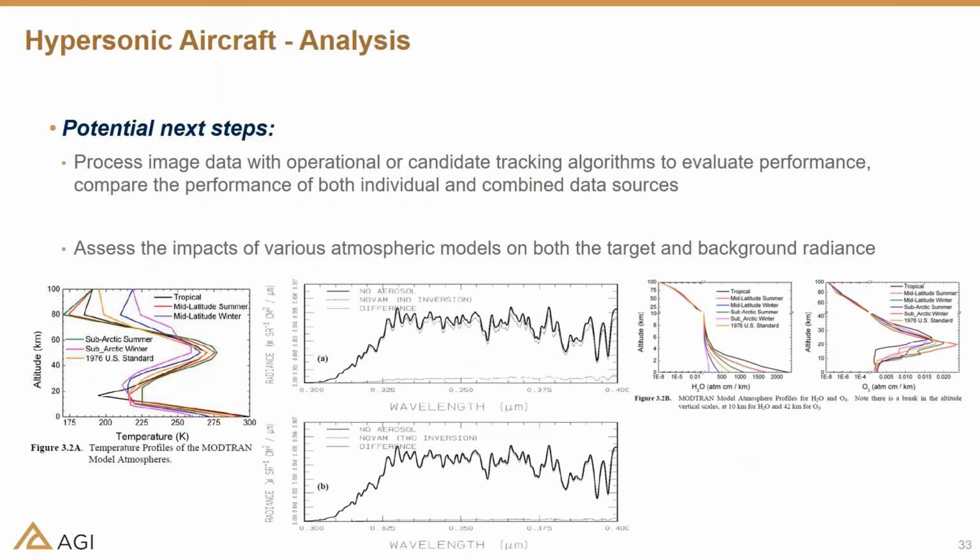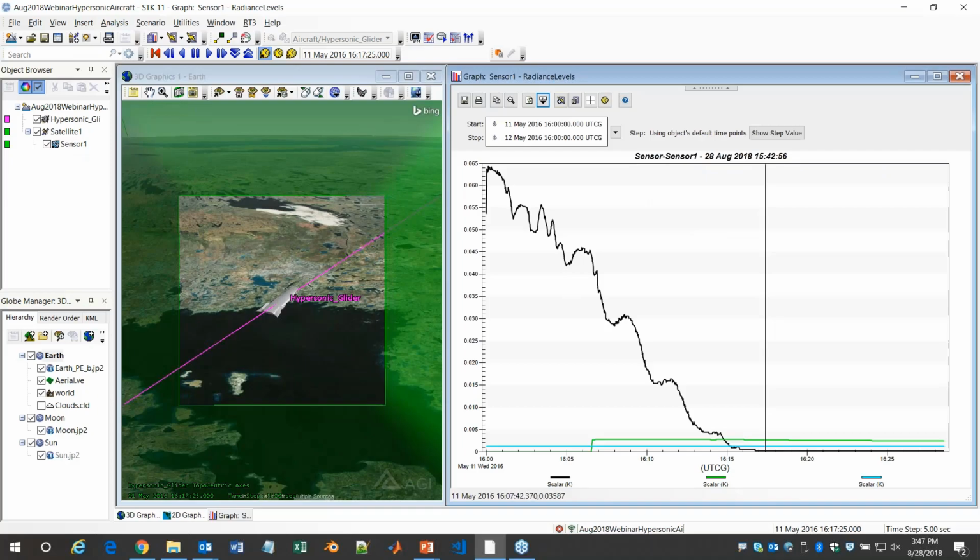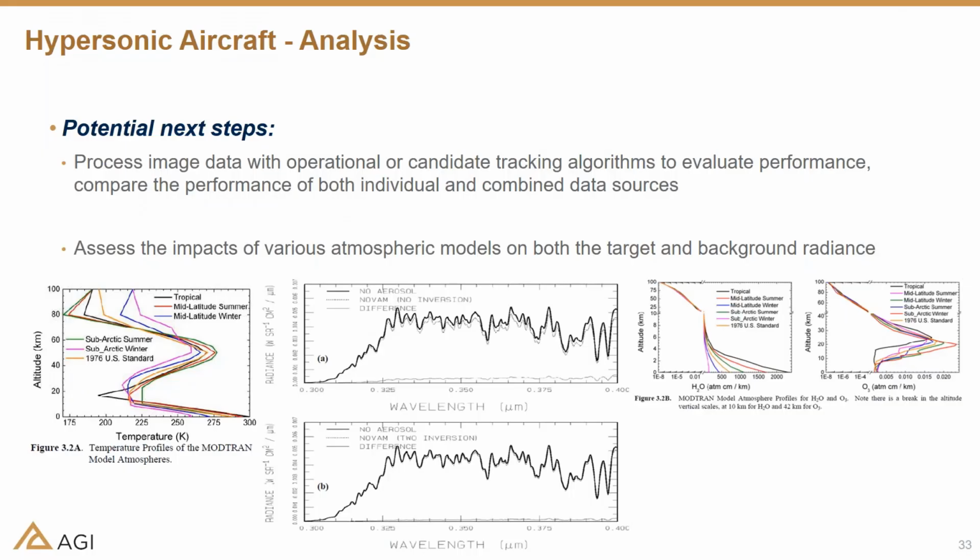How many satellites will we need in different orbits to be able to constantly get above this contrast level? And then similarly, once we've got a lot of that figured out, it's time to say, well, we're using a nominal atmosphere. What if we throw the kitchen sink at it? If we change the atmospheric properties, there are a few things that modifies. It modifies both the temperatures of our surfaces and the path radiance that we're going to be seeing optically.